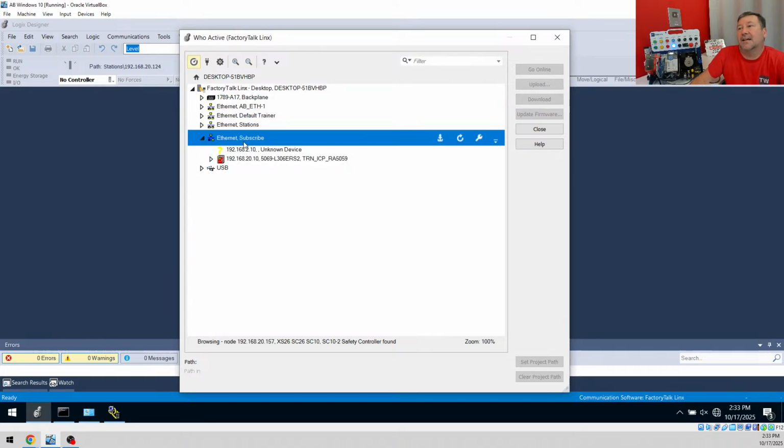And now we get this. Now, very important. Actually, I will do this in RsLinx too, just so we see a little bit of difference about the icons. First of all, we have a yellow question mark. Yellow question mark does mean this thing's unknown. It doesn't know what exactly is going on. But in this case, we also have a red little asterisk to the right of it.